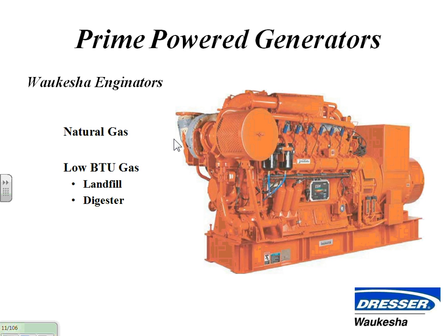How long can they run? Typically these things will run around the clock, as long as there's a fuel source. Typically what they'll do is if there's a time of year where you can't run with the digester gas, they have a natural gas backup that you can use if you still want to run the generator set. So there's systems like that in place, but it's designed to run as long as you need it.